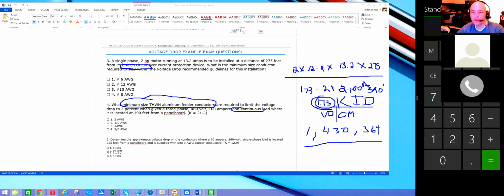And so my bottom number that I'm dealing with, the voltage drop, I'd take the 3-phase into consideration right here, but this number won't ever change. That table value is good for 3-phase or single phase, because if I were to do the volts down here times 1.73, I'd end up canceling them both out. If I do it on the top and on the bottom, it cancels out. So I just want to take it up here, and I don't want to take it down here. In other words, whatever it is in single phase, it'd be the same thing in 3-phase in this little step.